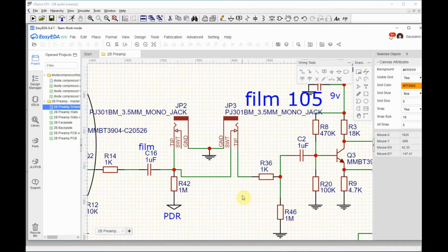I used to do it where I would switch both of them, but I found, honestly, from a practical standpoint, that I want to use these tip switch configurations as little as possible, because I found that they fail so often. You might not think of that if you're just building this circuit. Well, I think it's better to wire it this way, I think it's better to wire it that way. Well, in my opinion, I think it's better to use these switches on the tips as little as possible, because I've had them fail so frequently.